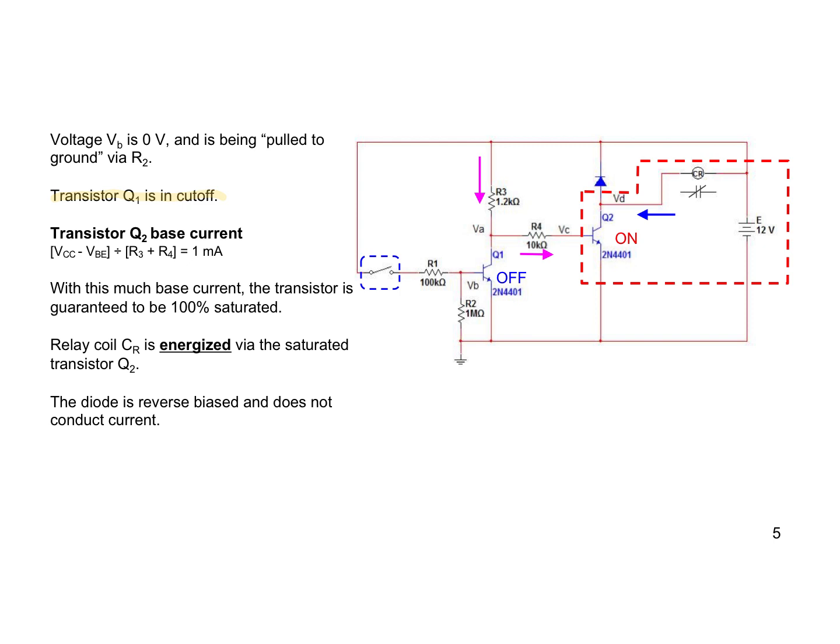So with transistor Q1 essentially acting like an open switch, you're ignoring the cutoff leakage current. Do you see that from the 12-volt power supply E, follow the arrows here, we have a current path down like that. So the transistor Q2 has sufficient base current to forward bias it, so therefore Q2 is turned on. And there's the formula for solving for the base current.